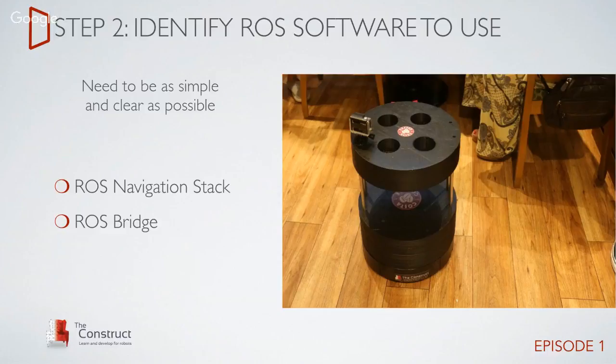And why is that? Because the person who is delivering the coffee to the robot has to indicate the location at which the robot has to move. And for that, we are going to use a very simple web page that contains all the tables. When the person clicks on one of the tables, this is a web event that has to be communicated to the ROS navigation stack. And for that, we are using ROS Bridge. ROS Bridge is the bridge between web elements and ROS. So that's why we only needed this software for the Barista.